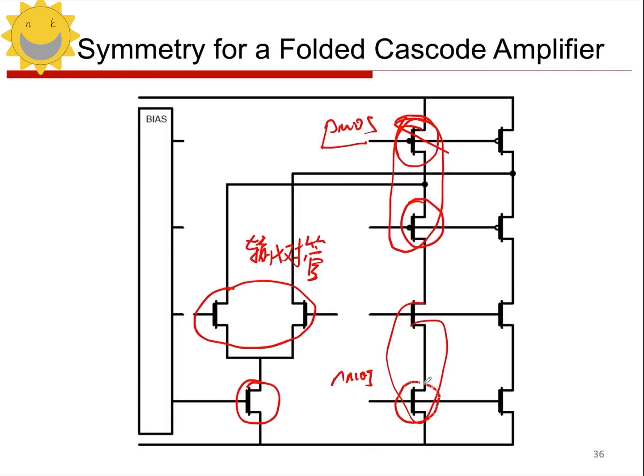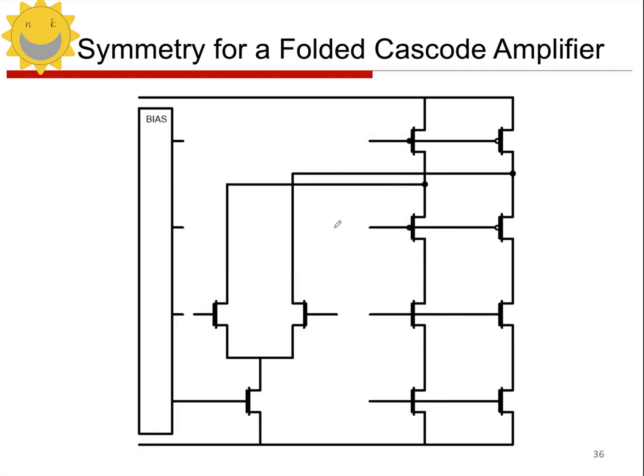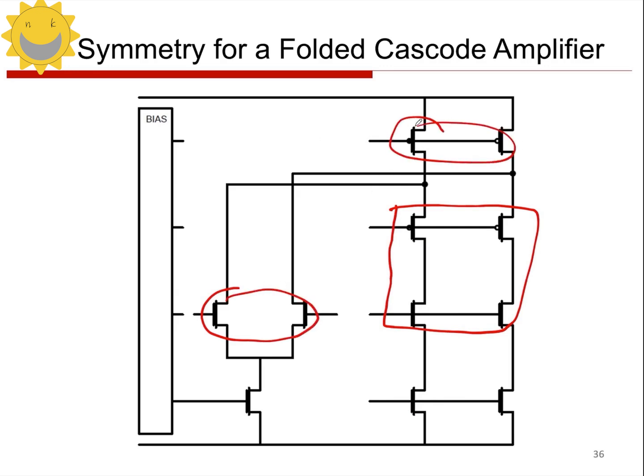Then underneath we have the NMOS current source along with an NMOS transistor as well. So what about the layout? Actually, the deviation of these four cascode components has a relatively small impact on our op-amp. So what is important? The important thing is the input pair, and the upper and lower current source transistors. Their deviations can have a significant impact on our operational amplifier.